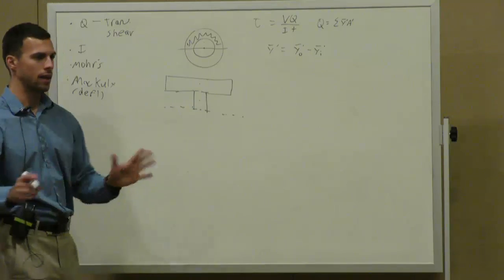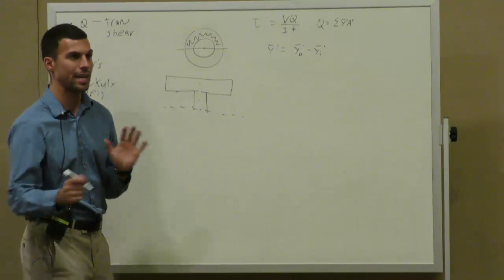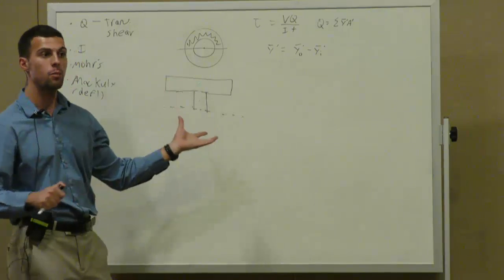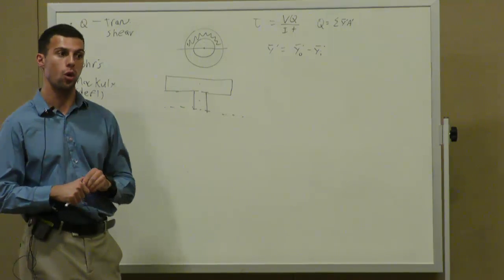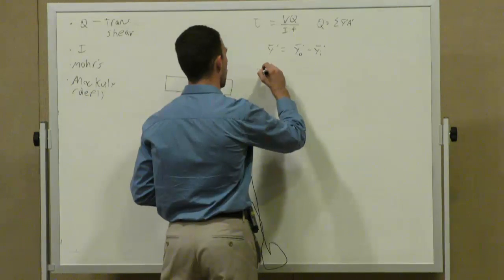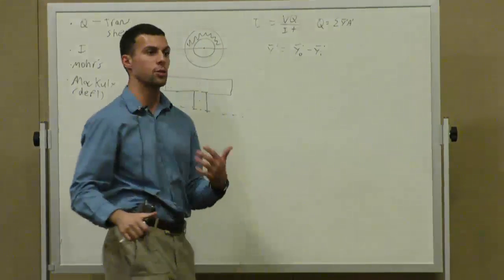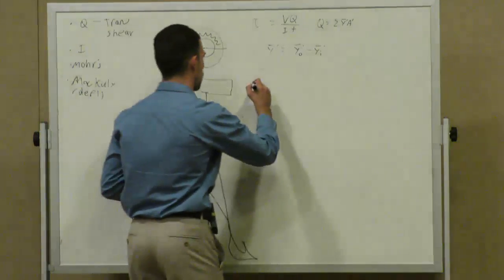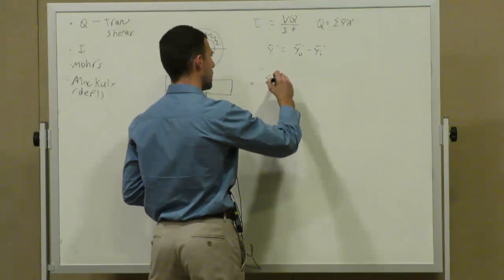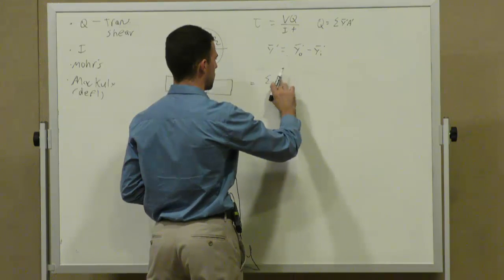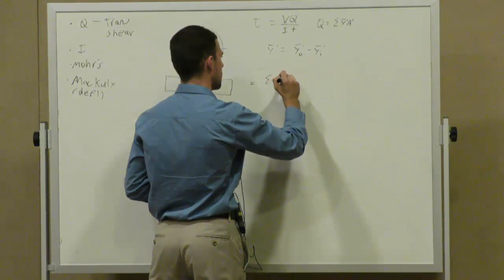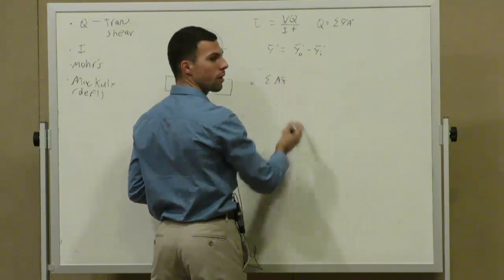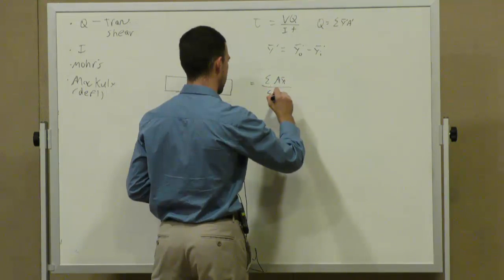Yes. So I had to sit there and do that in my head for a second. But yes, you add them up because we're subject to the law of superposition. It's the same way that you did it for the overall I-beam, or it's more akin to a T-beam. This is essentially a T-beam. So you do your sum of the area times the individual y bars over sum of the areas.